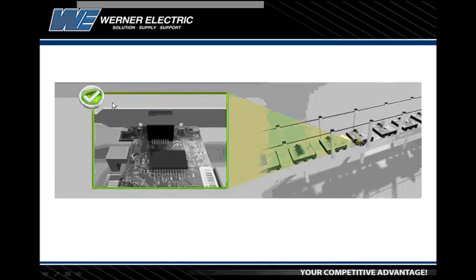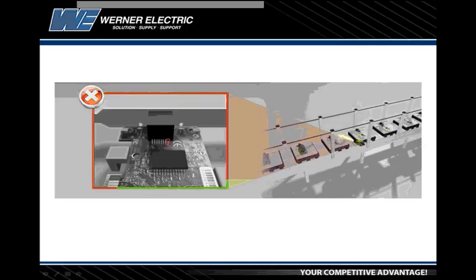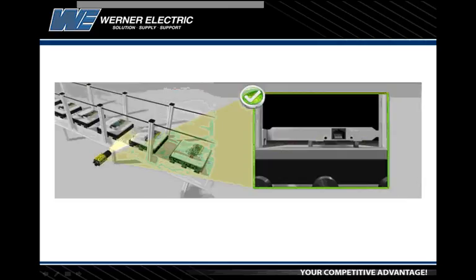Okay, here's a card like you might see inserted into any PC. It's an Ethernet card, I think. If we look down at the back of the connector with the vision system, we can verify that all 8 of the leads are going into the connector on the back of the unit. So there's a unit here that's failing because the 7 leads on the right are intact, but the 8th one is broken. And so that would be a non-functional unit.